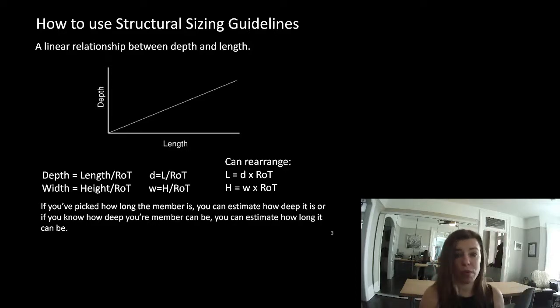There is a headroom issue. That is what bounds you. That is your limit. Well, then you can say, if I can only be this deep, I should be able to figure out the maximum length of beams I can use. And then you could set out your grid spacing based on that. But usually you are starting with a constraint of some sort in there. Sometimes it's a constraint you've decided on, like what is my grid spacing?